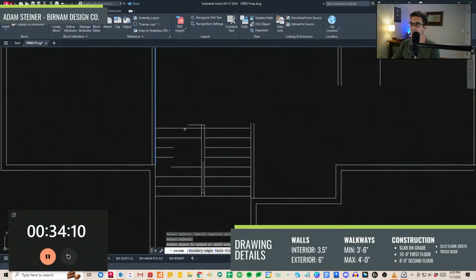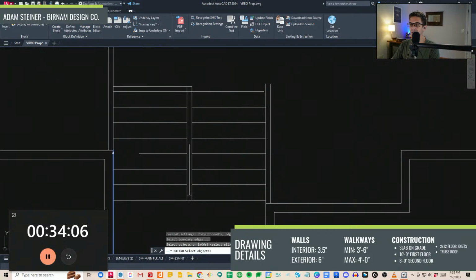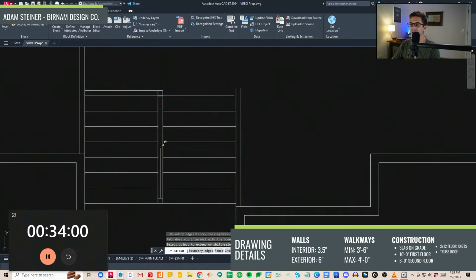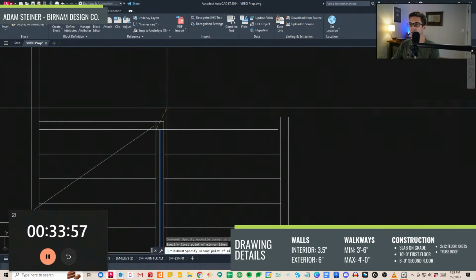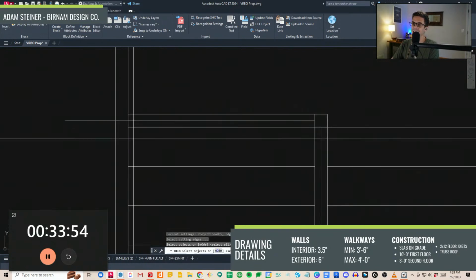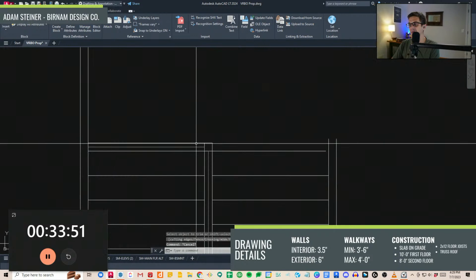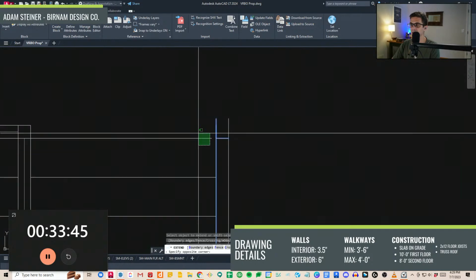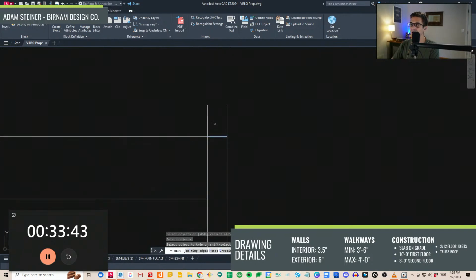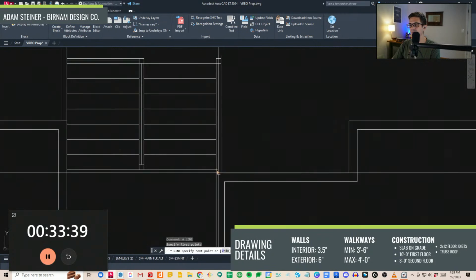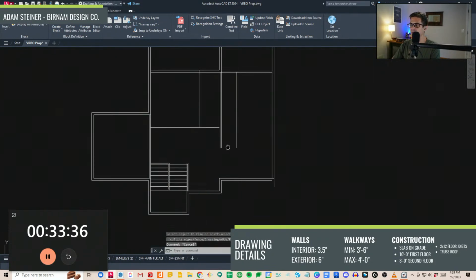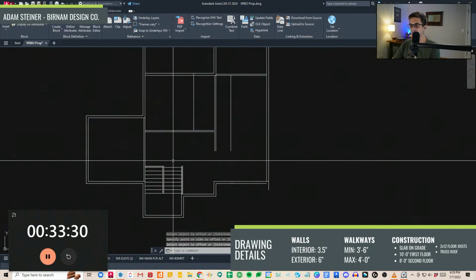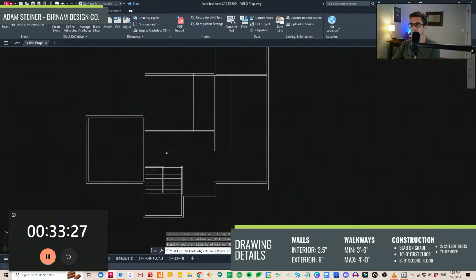But slab on grade, let me circle back to this. Slab on grade is, I really like it from a construction perspective because basements are not great when it comes to water management. Between water management and like air leakage, insulation, basement is usually your weakest spot, like all the connections between there and the main floor, and obviously it's below grade, so you're inviting water down there at times. Like, it just complicates things to have a basement. So if we can do it without one, I'm gonna try for that. I think you'll just get a lot more efficient house.